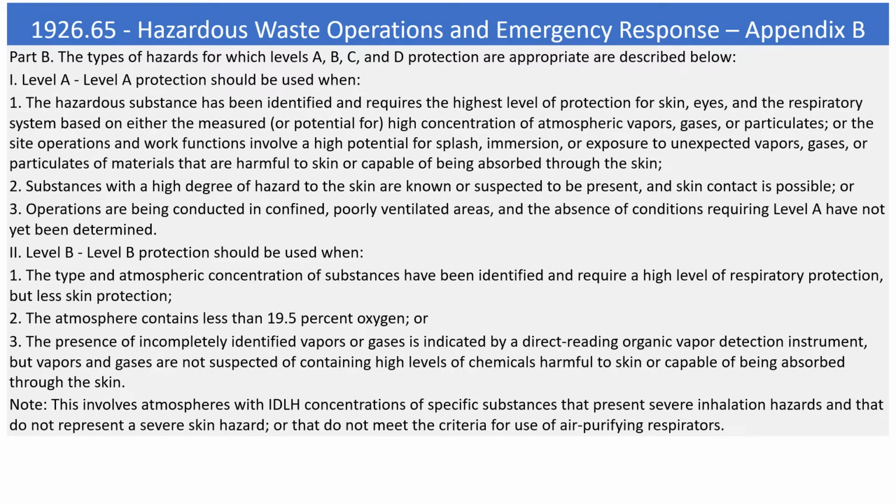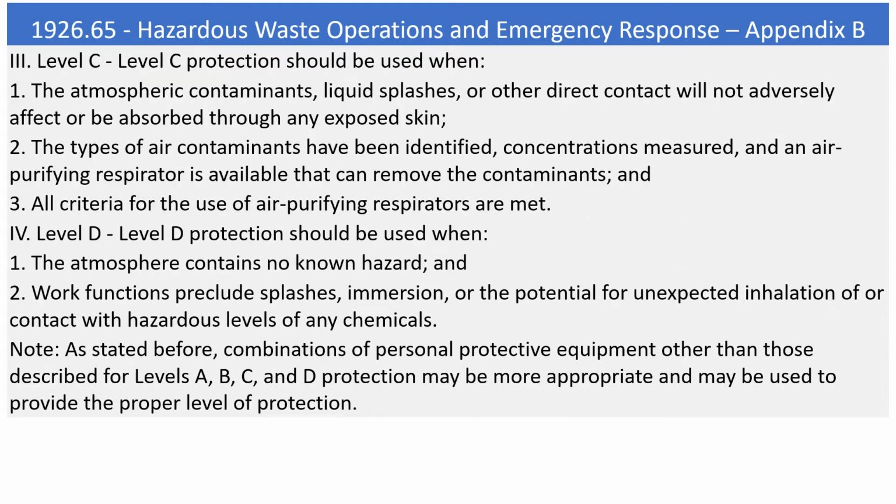Or 3. The presence of incompletely identified vapors or gases is indicated by a direct reading organic vapor detection instrument, but vapors and gases are not suspected of containing high levels of chemicals harmful to skin or capable of being absorbed through the skin. Note: this involves atmospheres with IDLH concentrations of specific substances that present severe inhalation hazards and that do not represent a severe skin hazard, or that do not meet the criteria for use of air purifying respirators.